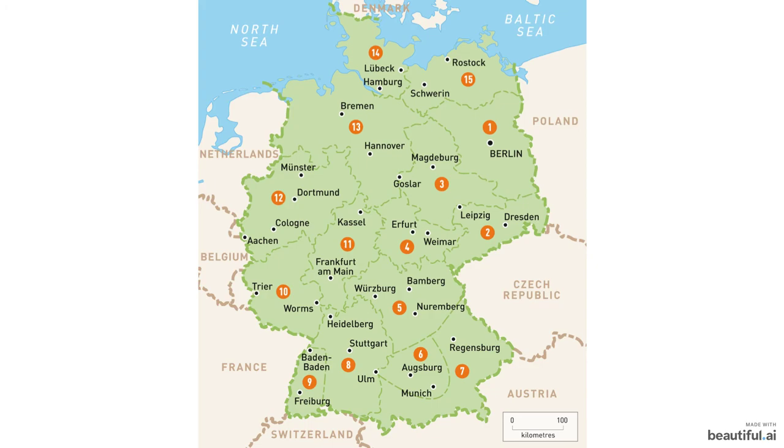The illuminator is also extremely flat. You may be wondering why there's a picture of Germany in front of you. Well, if the illuminator were the diameter of Germany, the highest equivalent mountain on the surface of the mirror would be just 1 millimeter high. And if that wasn't enough, the light passes through 8 more mirrors, and in the final stage of the optics is passed through water. Yes, water inside an electronic machine. It's called Immersion Lithography, and it increases the numerical aperture of the chip even further.